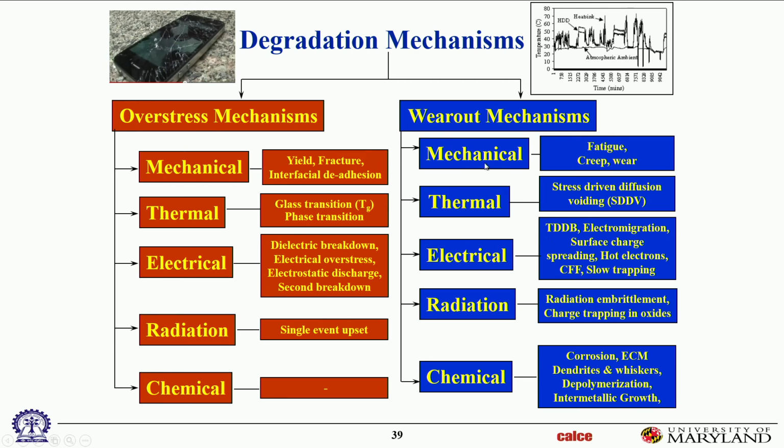The third is the red side and the blue side are interlinked. Meaning, let's say this glass has not fatigued but corroded over time. Glass does corrode, by the way, okay? Glass corrodes in harsh environments. Not something we think about very automatically. We think, oh, glass, that doesn't corrode, metal corrodes. Glass corrodes, which means its properties degrade over time if it's exposed to a harsh environment.